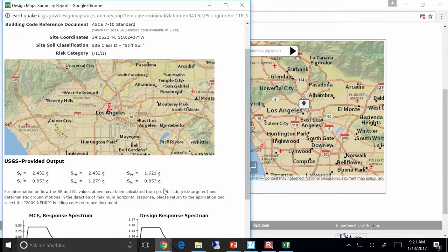So to force failure in the beams, to make sure that the beams fail before the columns do, we take the beam and cut out a small piece of it. We create a weak spot in the beam so that when the earthquake happens, all the failure gets concentrated right there. We actually do something quite similar in vehicles.